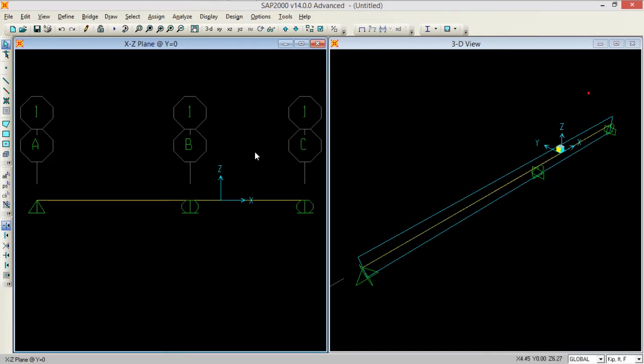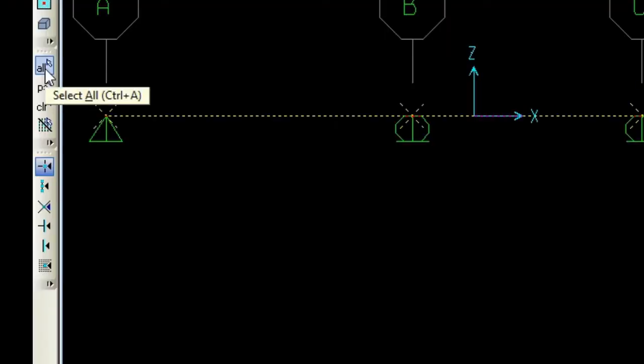If you move through this window, look, if you are moving from right to left, everything intersecting the window will be selected like we did in AutoCAD, and if we move from left to right, the things coming in between the window will be selected like this joint. So if I'm going from left to right, all things are selected, but if I'm going from this to right, I have to select this as a whole, right? So you have to just press select all, or you can also press this button, look, select all as well.